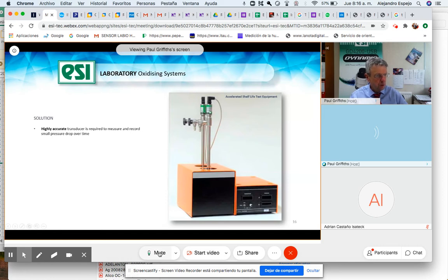They wanted the unit to be as small as possible. And this has a millivolt output. So their electronics, their little box of tricks here, it takes a millivolt input. And it was very, very specific millivolts. It was actually 4.7 millivolts per volt.